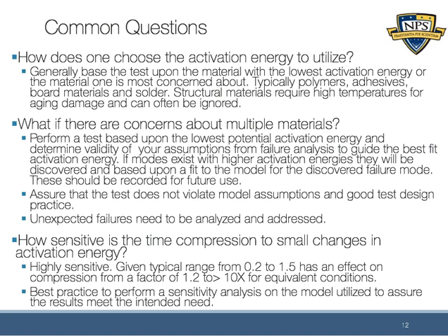So there are a couple of common questions that come up when using these types of models, and I wanted to address those in a question and answer format here. First of all, how does someone choose an activation energy to utilize? Well, I've shown you how to pick it, right? There are some resources. We choose it based on the material. And it depends. If you have a part, the kicker might be that the part has multiple materials in it.